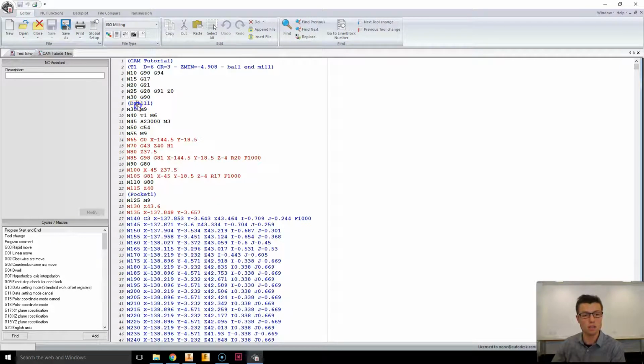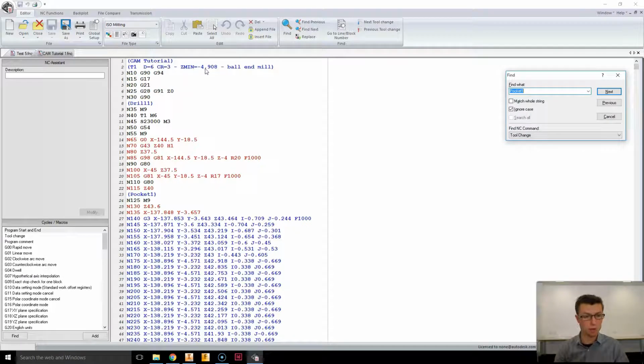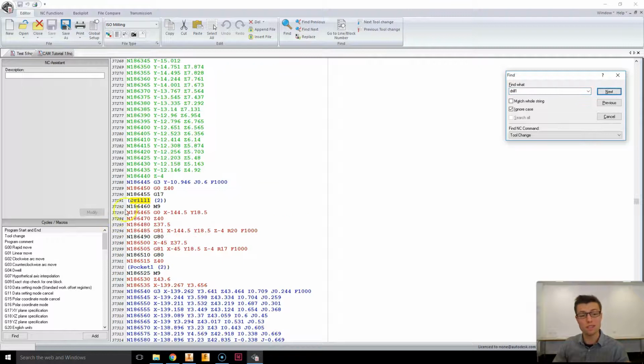And you can see there's certain elements in it that are informational, like this. Drill 1, that's the drill program. Pocket 1, that's the pocket program. You could be guaranteed there's a parallel one. What we're going to do is we're going to go and customize this slightly. To do that, we're going to use the Control F program, and we're going to type in drill 1 again, because we duplicated the drill. So there's the first one, and then this is drill 1, and then it's in brackets 2, the second one. Now, just above drill 2, we're going to enter in a new bit of code.